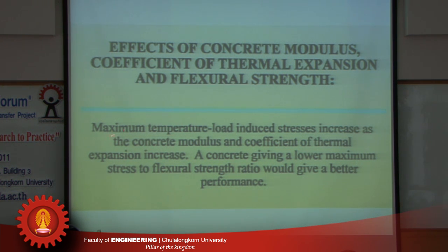Okay? So here's my general statement. Maximum temperature-induced stress, which means the maximum stress under the critical condition, increases as the concrete modulus and coefficient of thermal expansion increase. So if you have a concrete with a high elastic modulus and with a high coefficient of thermal expansion, your expected stress is going to be higher.